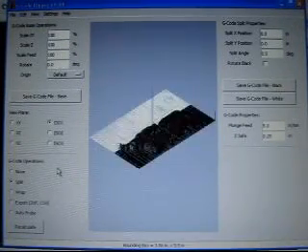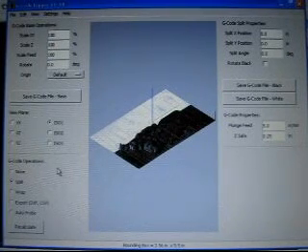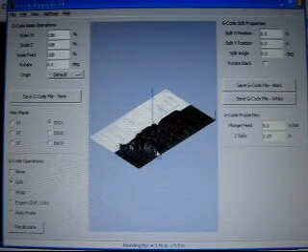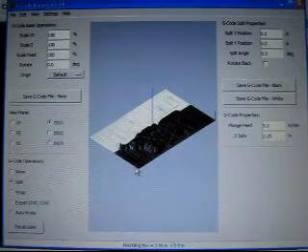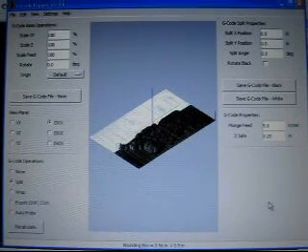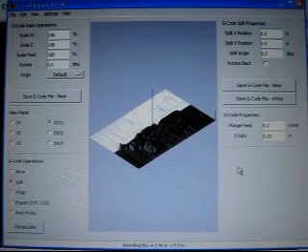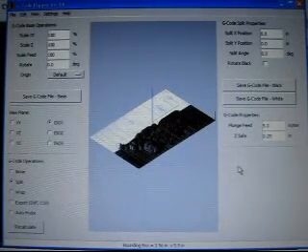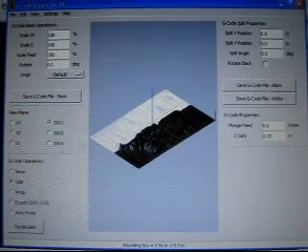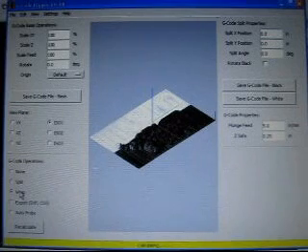If you need to split your G-code into a smaller file, which is a handy thing if you have a machine like mine, where you can actually download the program but you don't have that much space to download it. You can make the file smaller and then run it in 2 sections, because the machine runs smoother when it's got the program downloaded into it. Alright, and this is your parameters for splitting and so forth. Now this is kind of interesting.